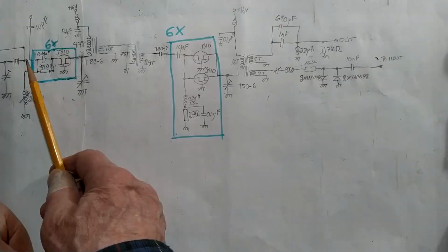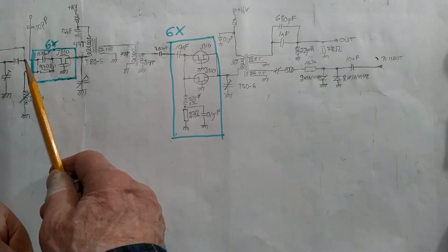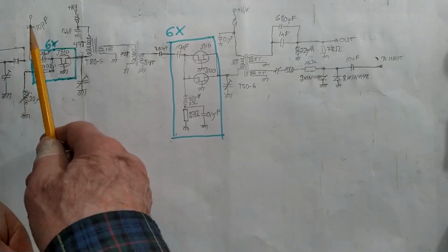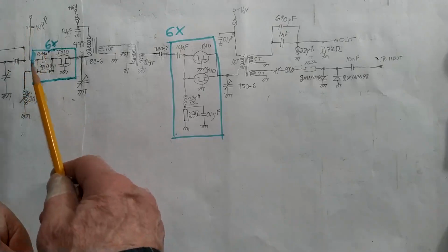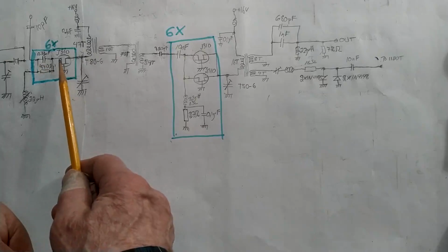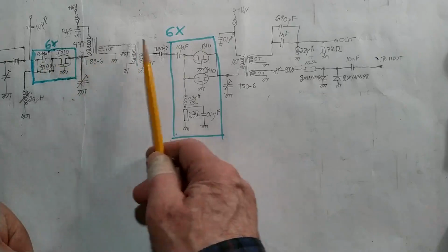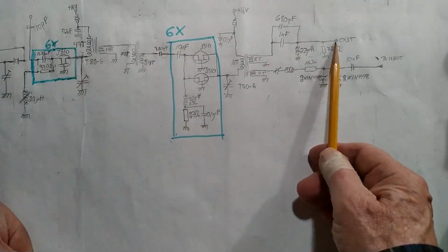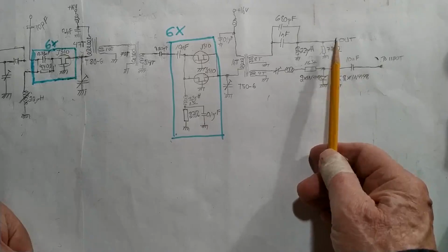I'm checking the amplifier in the interferometer, injecting a signal through 10 pF into the sources of the 6 parallel J310. And then I look at the normal output signal, the one that I am analyzing when the thing runs as an oscillator.